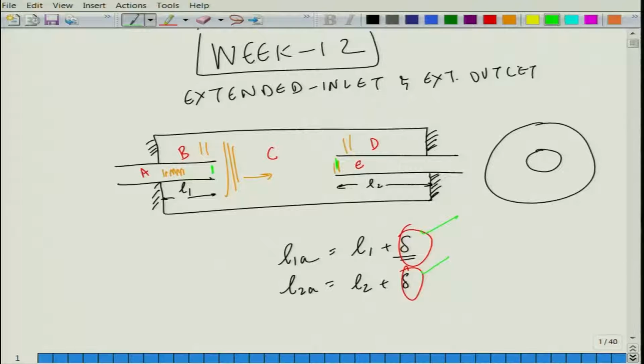For now, these deltas were computed using the expressions presented in the paper by Chaitanya and Munjal in Applied Acoustics, which was done using 3-dimensional finite element analysis. But there are other techniques also, like analytical techniques, or mode matching techniques, numerical mode matching techniques, a topic I have reserved exclusively for the next course.